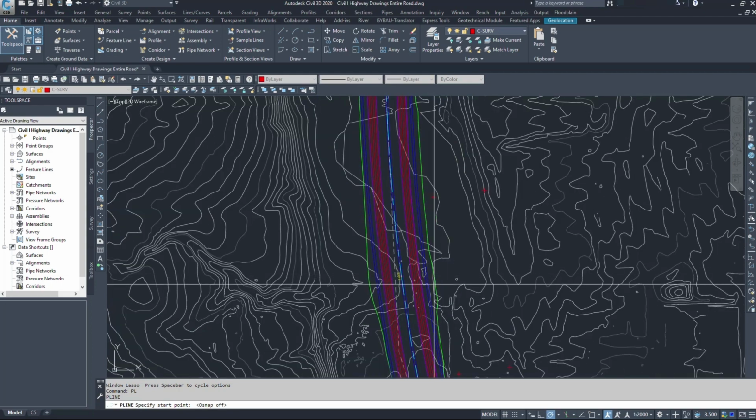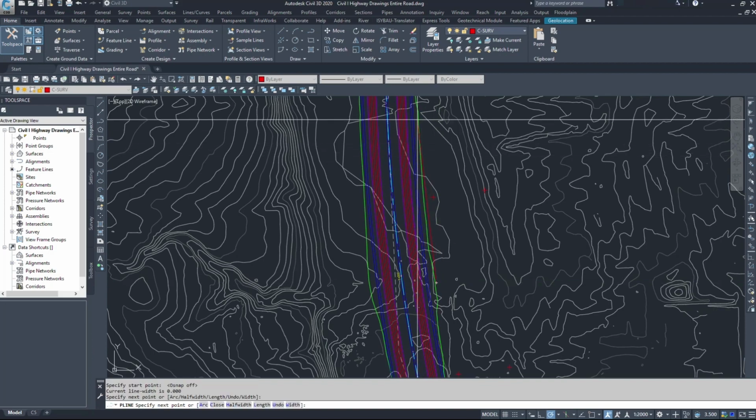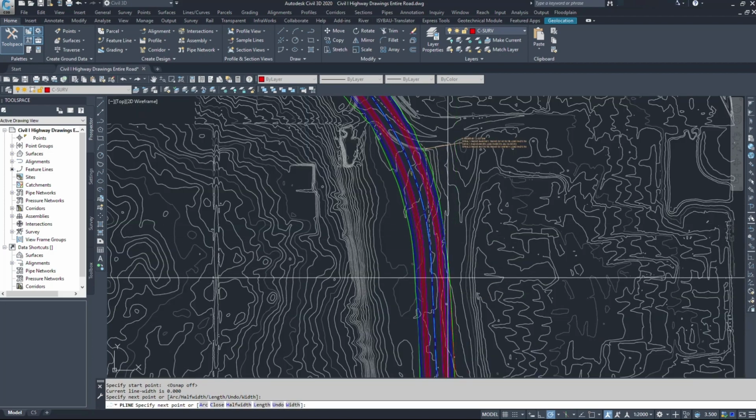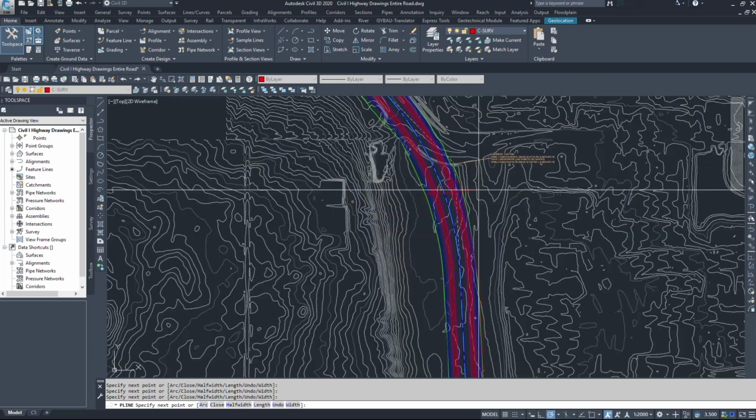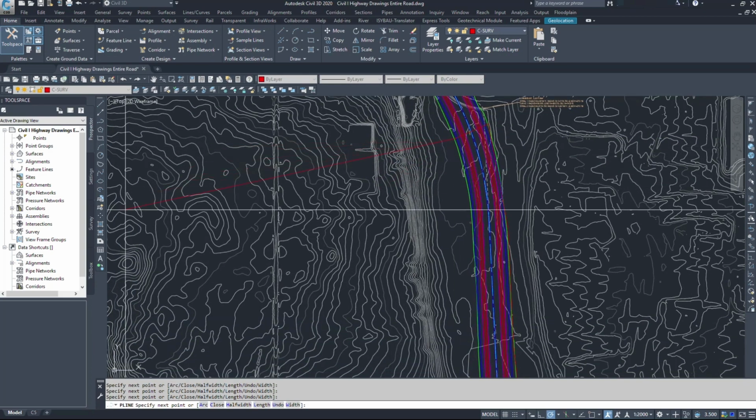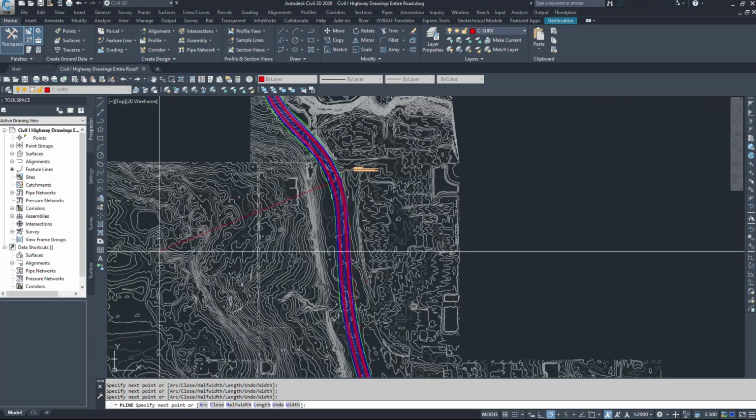So 3,000, all the water on this road. And again, I'm just going to do this very roughly to get an area. Station 4,000 is the high point. Now we kind of have to guesstimate what part of this land is sloping towards the road. We could turn on slope arrows, but that's just some more unneeded information.